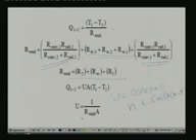You probably might have heard of this when you are doing heat transfer calculations. When I am comparing this equation with this equation, you find that the overall heat transfer coefficient is nothing but 1 by R total into A. So, if you know the resistances, you can calculate the overall heat transfer coefficient. The concept of overall heat transfer coefficient will be used very widely when we are designing the heat exchangers.